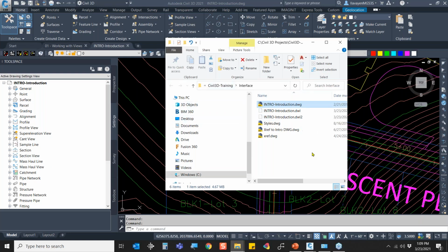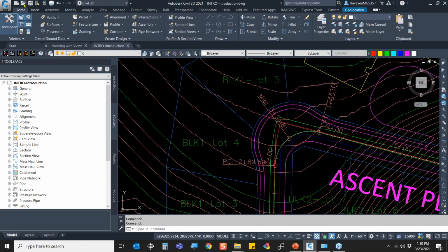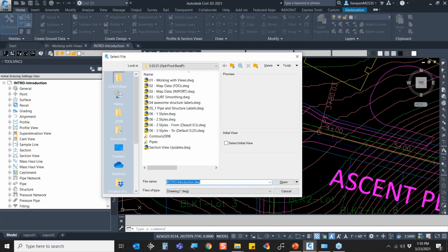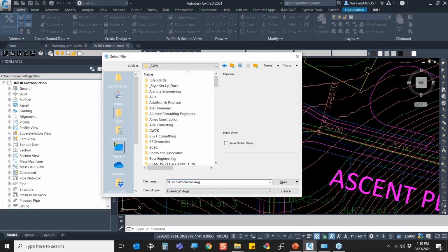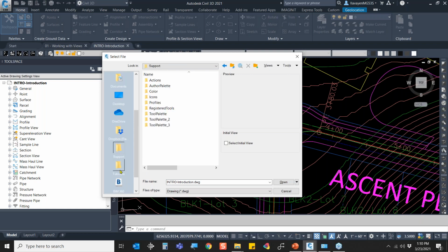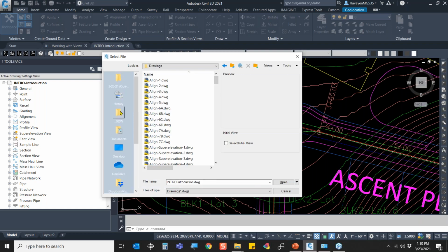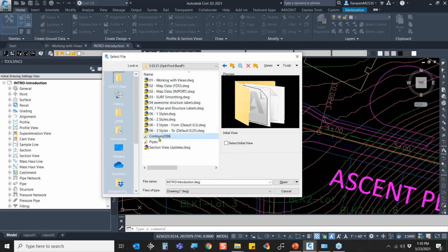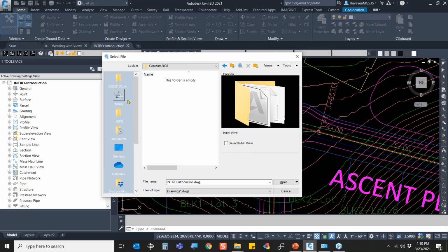I like that. That way I can explore perhaps any other drawings, drag and drop them right in here if I wanted to. Or in this case, what I also have is, of course, the ability of just a standard open, going up here to the quick access toolbar and finding a drawing. What I often do is save folders here. That way I can go to and find a folder that I want to. Now you may have the out of the box locations. And if you have a particular folder you want to get into, what you're able to do is find that folder, right click, and simply say add current folder. Of course, once you add, you also have the option of removing.